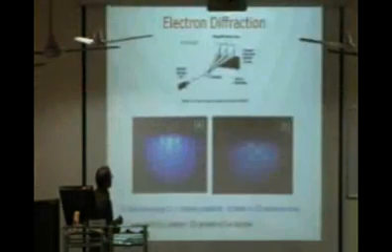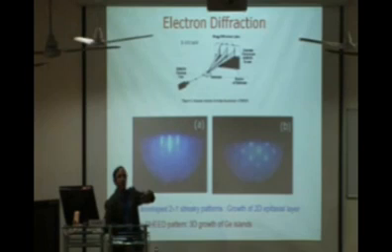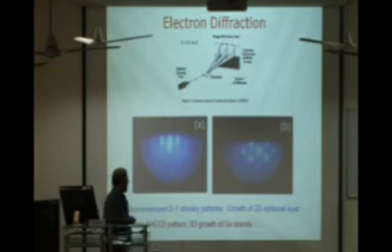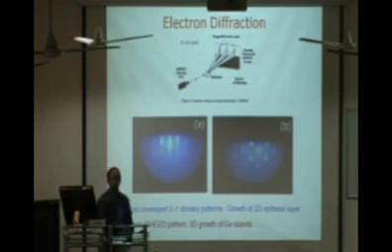So how do we know that, during self-assembly, a transition has taken place from 2 dimensions to 3 dimensions? By taking an in situ electron diffraction pattern of the growing material. When these materials are grown, we have an electron source called the reflection high energy electron gun, which glances on the substrate and gives the electron diffraction pattern on a phosphor screen.